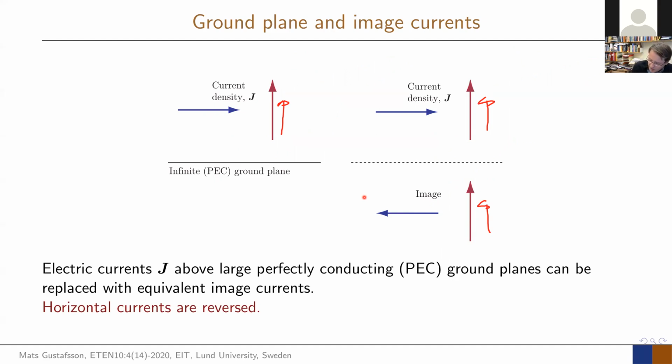So if we take this, it actually goes back to a ground plane. If I say here, it says a charge. If I put a plus charge there, then I always get an image charge here, which is minus Q. So instead of a current, if you do a charge, currents are charges that are moving, then I get an image that is minus of that one. And now we could say that you had 2 of these. So let's add another one. Let's add one there too, and that is then minus Q. Then that minus Q will have something sitting up there, and that is then plus Q.